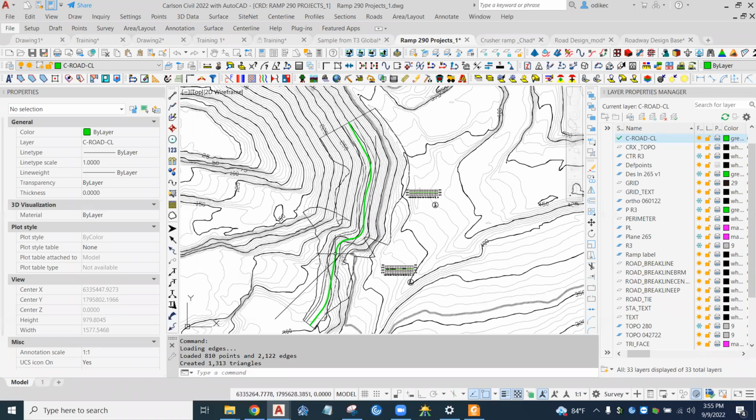The other solution is, like I said, where everything is in cut, you don't have any fill. We would have to scoot the center line back into the wall, right? Yes, scoot it back into the wall some more. Or lower the elevation of it.